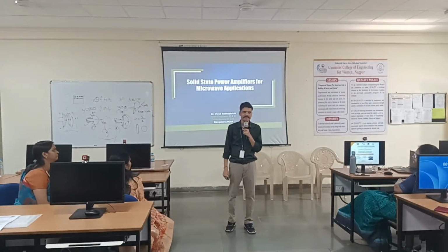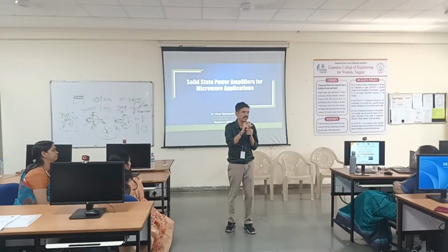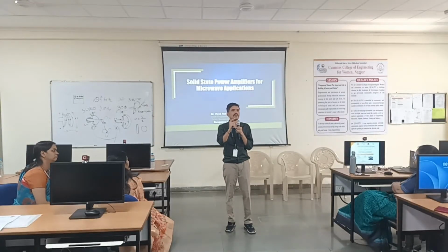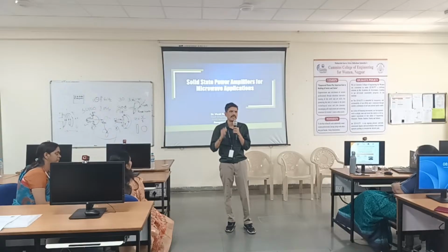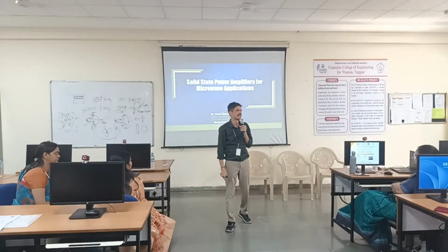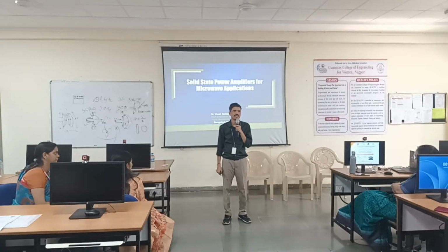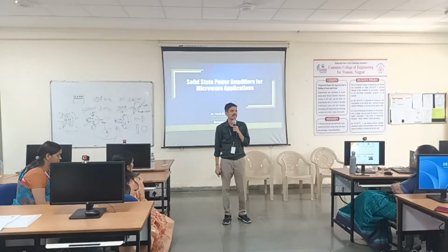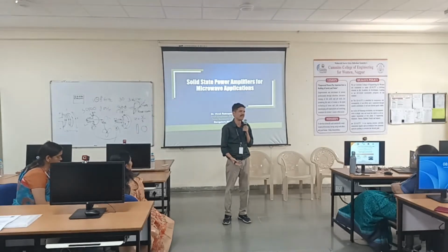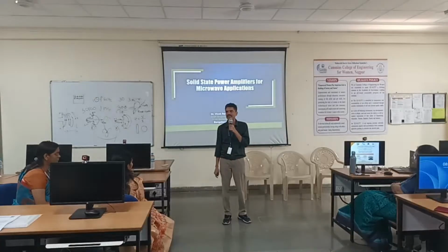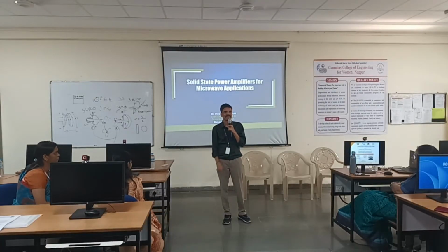Let's say you have to design an amplifier of 30 dB gain, 5 dB of noise figure, 1 gigahertz of bandwidth, center frequency of 3.5 gigahertz. Let's say a 500-watt amplifier. What is the application? DRDO people will do that for defense, their missiles, their radars.